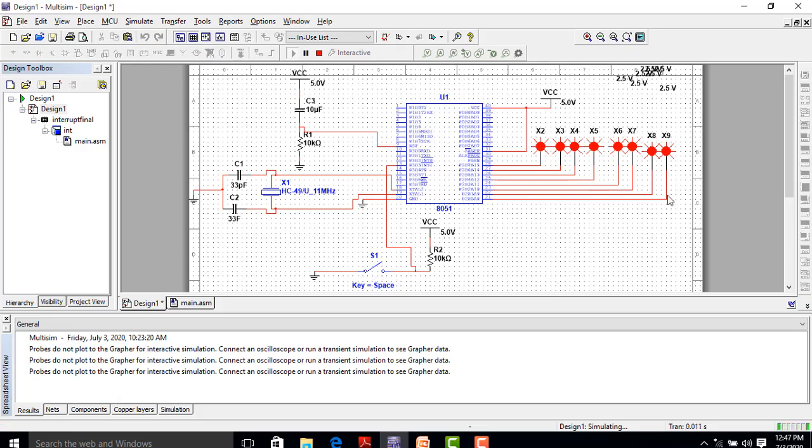By default, let's see. I'm pressing it the first time. Okay, so only this LED should glow, the rest of them should be 0. This should glow and the rest become 0. So it will indicate only 1. I'm pressing it. Let's see what happens. You can check it out. What happened? The first time the interrupt has occurred. Let's press again. Now this bit should become 1. This should become 0 because in binary it will be 2 now. Press it. We get 2. Two times the interrupt has occurred.